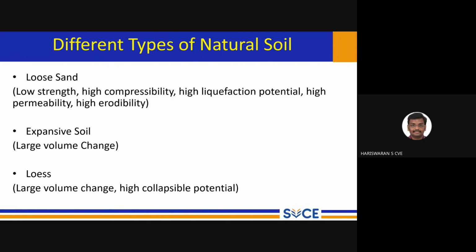The next type of problem is called expansive clay, right? Soft clay has more chance to undergo compression and more settlement. But expansive soil creates the most dangerous thing. There will be more volume change, it may expand, it may swell when it has contact with water.